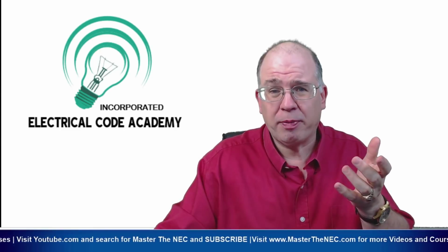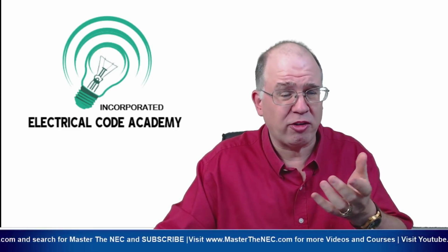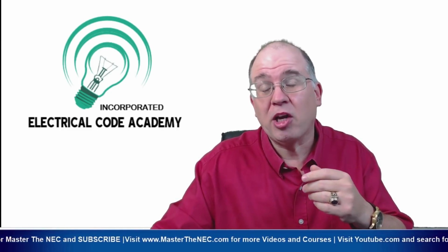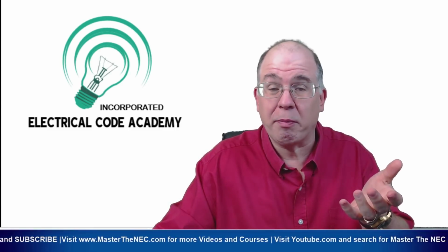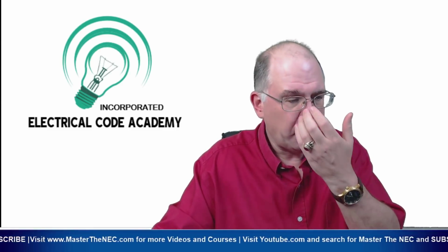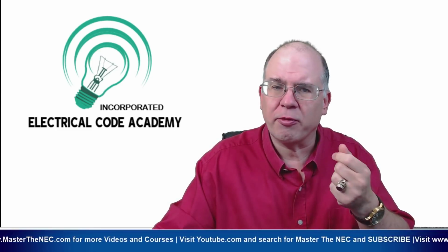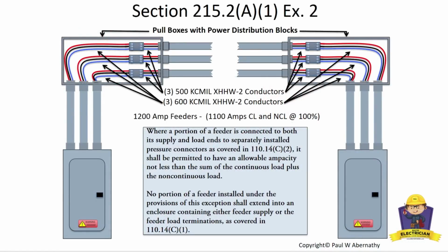I can for fire pumps, and I could argue that a motor is not going to operate efficiently if you have a certain voltage that falls outside of its operating parameter, but the code just doesn't say anything about that. We know that it could affect it and burn it up. You're going to be replacing them forever. So, voltage drop's got to be considered. But we increase conductor sizes for many, many things too, not just voltage drop. Engineer specifications and whatnot. Anyway, so here's the allowance in that application.